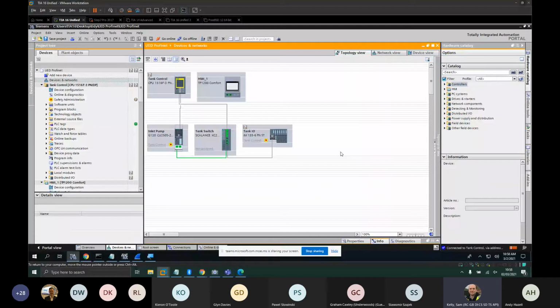And we'll see that one of the cables is missing. Yep, fair enough, that's fine. So I'd go back, plug the cable in or fix the cable if someone had cut through it, whatever. The network will reconfigure. So if we still had the update time less than 200 milliseconds, it would trip again because it's doing another reconfigure. But because we've increased that IO cycle time, we don't have that problem anymore.